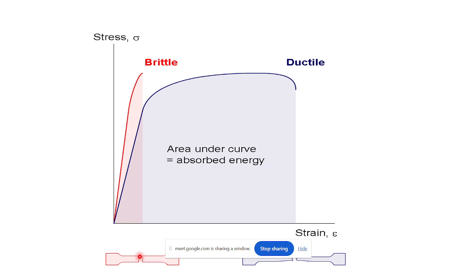For brittle type of failure, it will be like this. There will be no stress concentration point. The surface will be very smooth. So from there you may predict what is the problem in your material, or what will be the change in the formulation. For the ductile type, it will not be a very smooth surface. So you are stretching, so stress concentration will generate, and finally after certain time it will break.